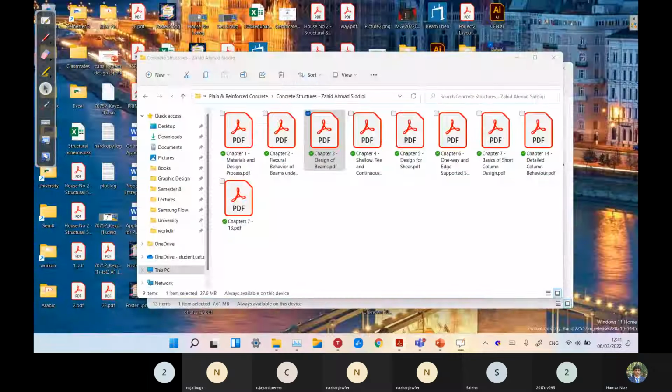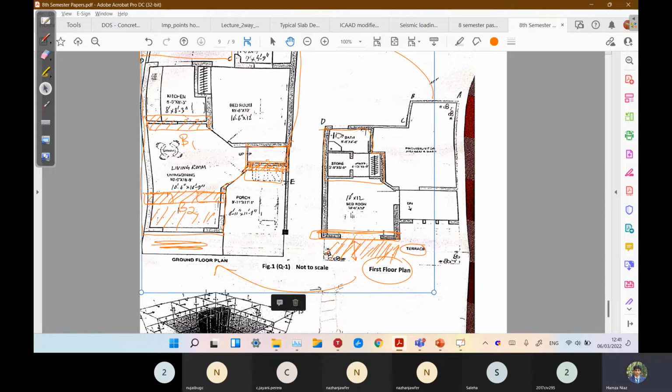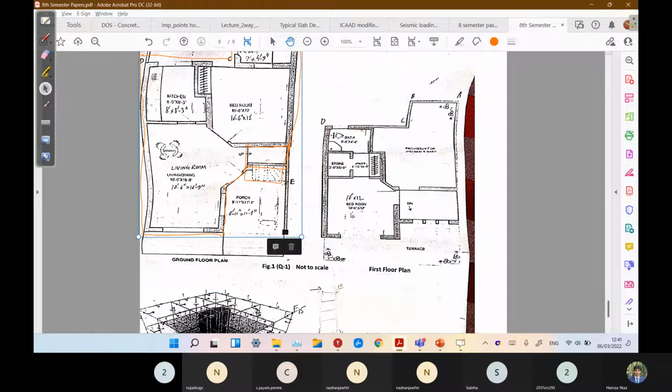So in this case, if I move the previous beam, this portion we can either remove or retain. That's no issue. But the bottom portion must be removed because we have to move to the first floor. So either we can provide an open void like this, where this cross shows the open void, or we can provide a whole void for stairs like this one. We remove the whole slab of the stairs.